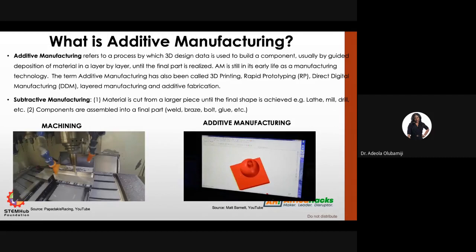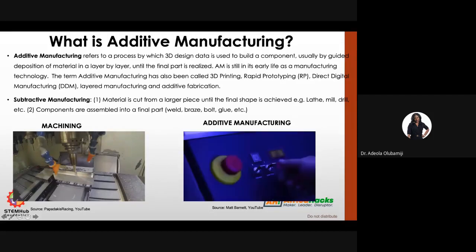But the 3D printing one is a layer by layer manufacturing process where, instead of dumping a lot of material there and tracing out the part, you just need your material to be put in the right place. So you use smaller amounts of material when you are 3D printing, and you don't waste a lot of material. This technology became very attractive to manufacturers because you save on waste, and it also helps with some very good things that I will talk about in terms of complexity, durability increase, and so on.